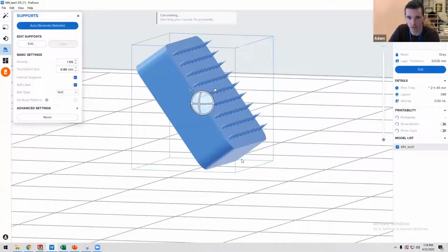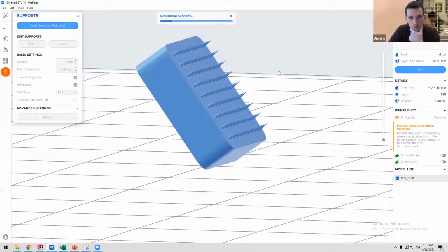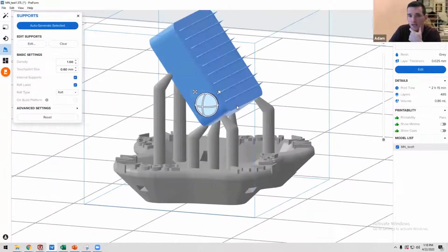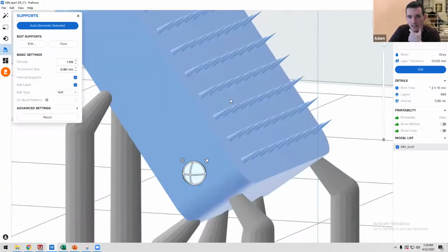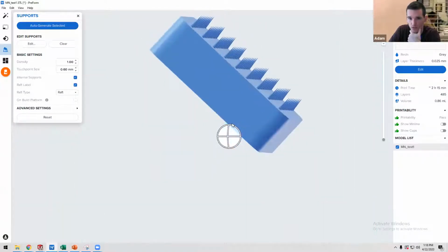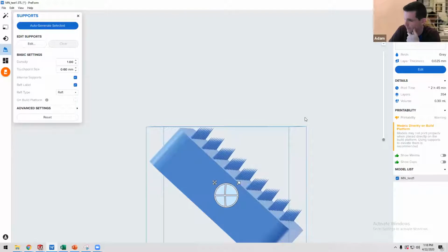Get down to 25 microns. Okay, when I generate supports on this, that one looks okay actually, so I could print that. If I go any steeper, this may actually not generate because the tips are so fine that it could not resolve in the software algorithm. So I would recommend trying to go at like a 45, and you'll get sharp microneedles if you're doing that.